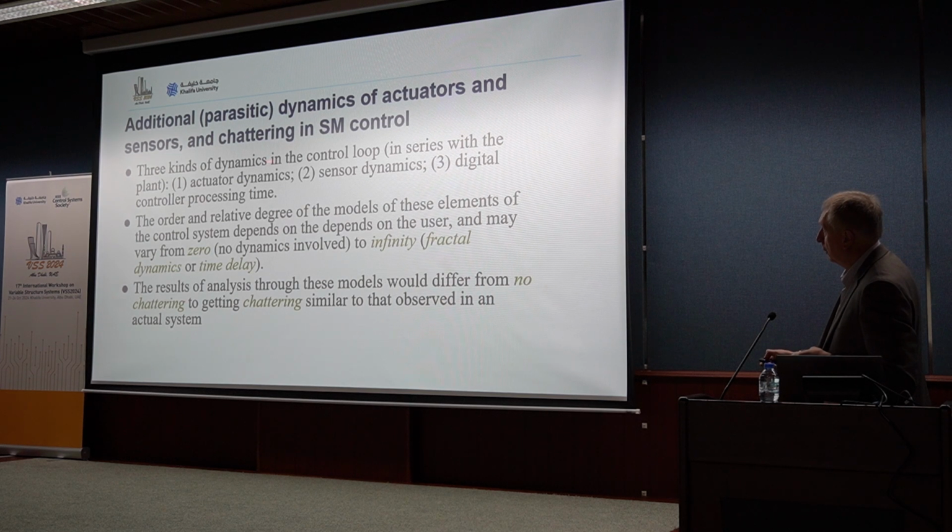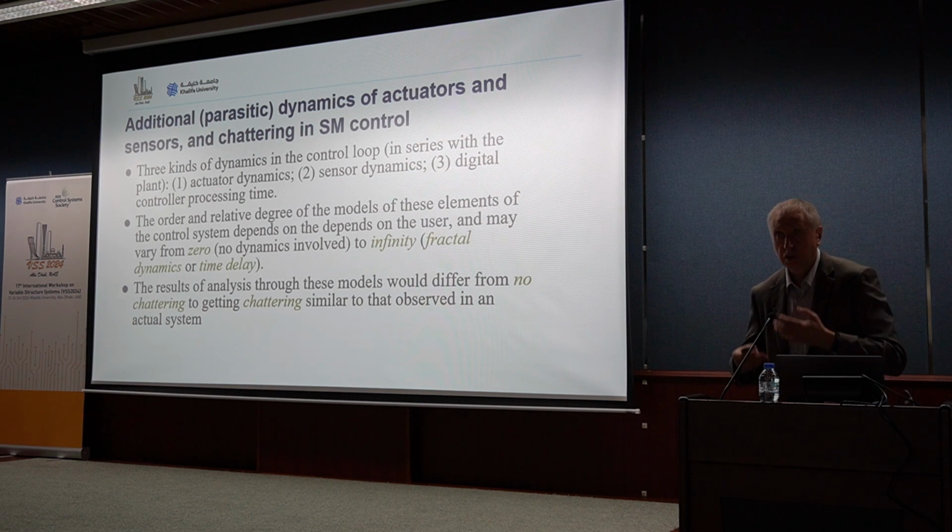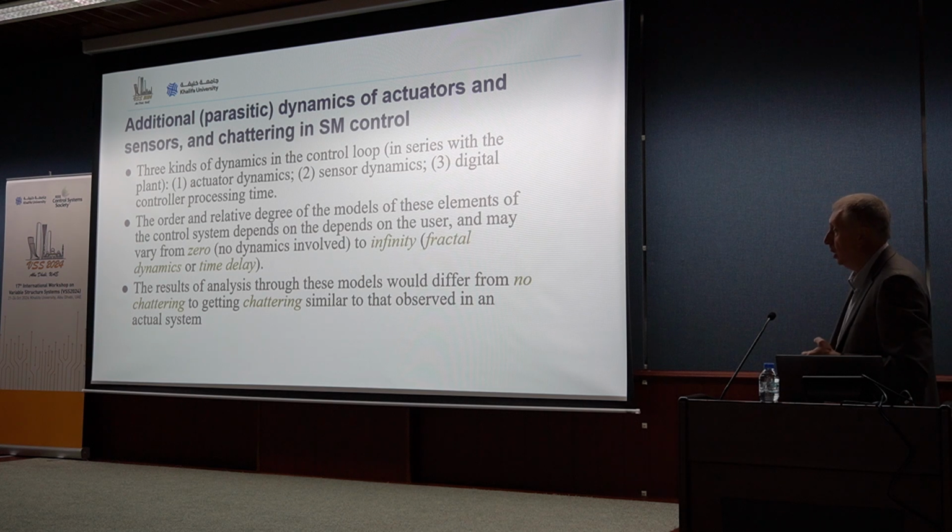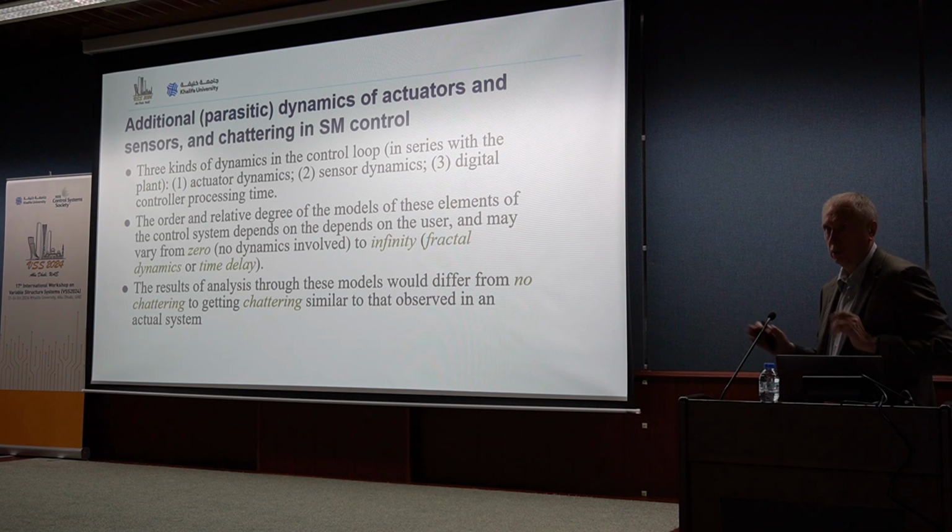Because we have these additional dynamics in the loop in series with the plant, which are actuator dynamics, sensor dynamics, or even the digital controller processing time, which introduces a delay, we will have this effect of intersection by the Nyquist plot of the negative reciprocal of the describing function. And this happens due to the increase of the relative degree of the linear part of the system,